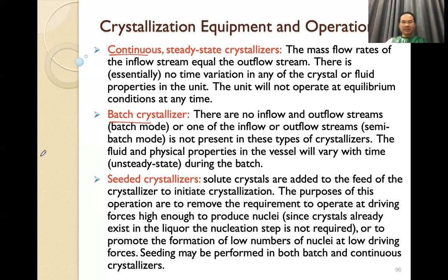And another kind of crystallizer, we call this seeded crystallization. We have seeded and unseeded. Seeded means we would like to grow the crystal to the largest size. For this case, we add some crystals into the clear solution to make it a bigger size.